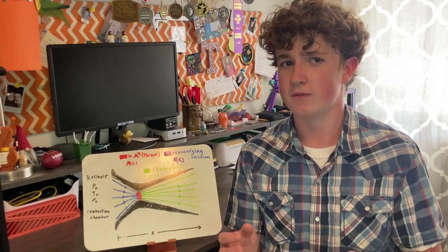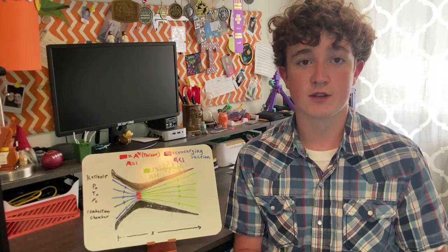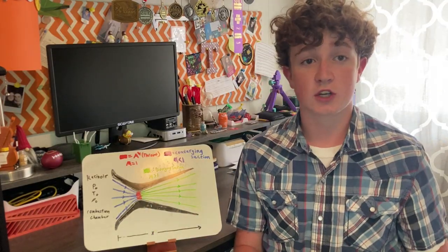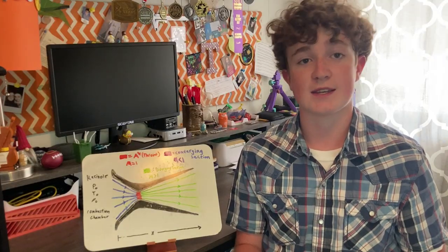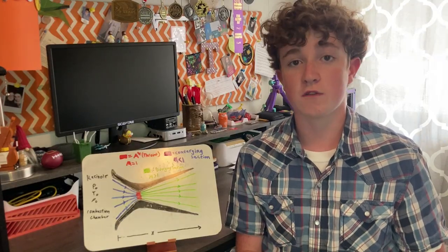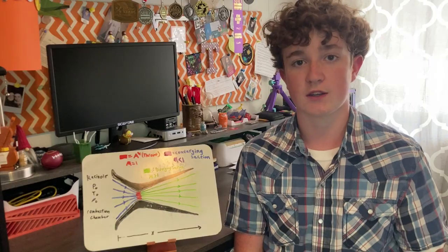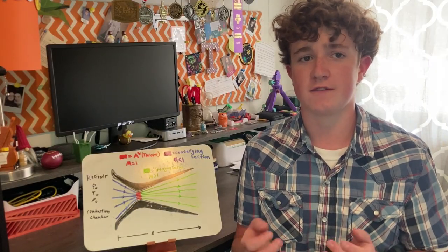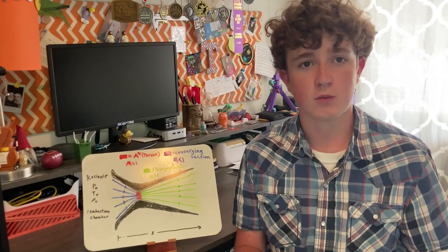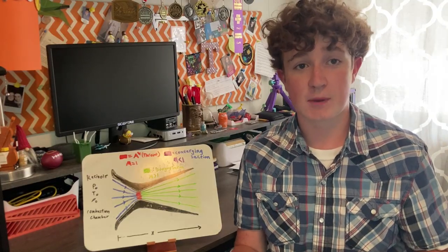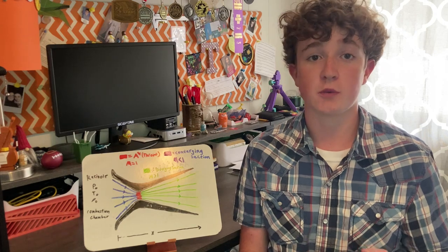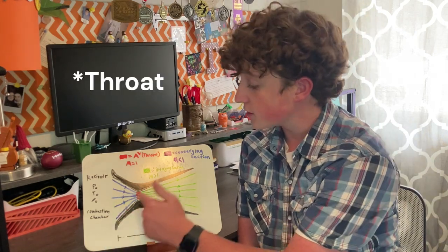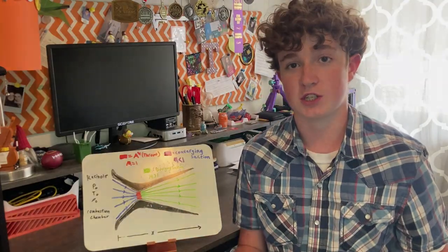It's pretty weird. The smallest area in a nozzle is called the throat, right here where the red marker is, and is ideally the critical spot where the fluid velocity is Mach 1. This is called choke flow and is most efficient for a rocket nozzle. Any further decrease in area will actually result in the slowing of the fluid. The throat is critical while designing a nozzle, and is what expansion ratio is based off of, and is where flow reaches supersonic speeds. The decrease in area from the combustion chamber to the nozzle is called the converging section.